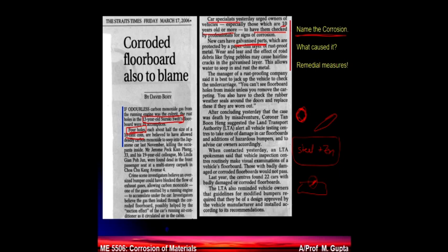When they used to come out from the sea, they used to come with salt deposits. Initially, when the understanding was not there, they would come out, be parked in a closed space, and they started to see corrosion happening under these deposits. So they realized it and started to maintain it.